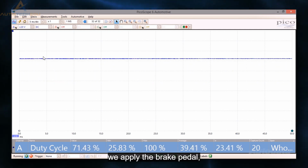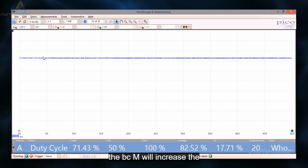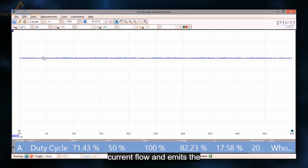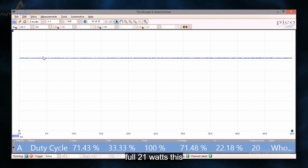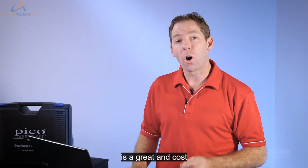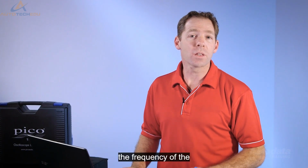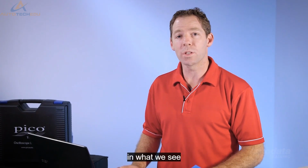When we apply the brake pedal, the BCM will increase the duty cycle to 100%. The lamp now has full current flow and emits the full 21 watts. This is a great and cost-effective way to control lighting. But it's not just the duty cycle that does this. The frequency of the control plays a major role in what we see.